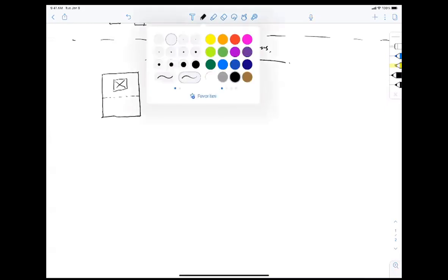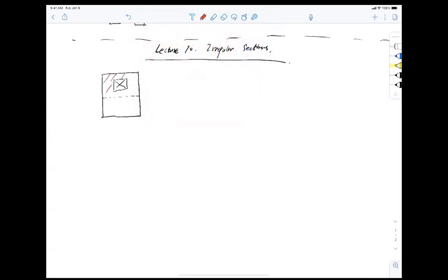So the whole thing tells me that the compressive section is going to be here with a hole punctured in the middle, all right? So my job, first thing, is to find a neutral axis. And then with the neutral axis, I can see the strain diagram, all right? And this is the compressive zone C here. And again, if I have some reinforcement, let's assume I have a chunk of reinforcement AS, then the depth of the beam is somewhere here, and the depth is called DS.